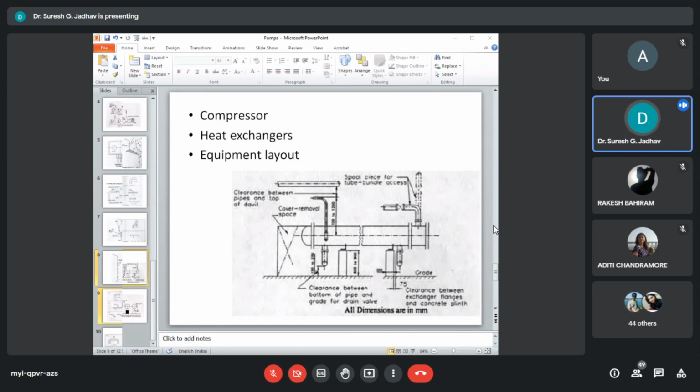Next concept: an exchanger connecting two equipments, one on the shell side and the other on the tube side, located at a distance, should be placed where two streams meet and on that side of the yard where the majority of related equipment is placed.